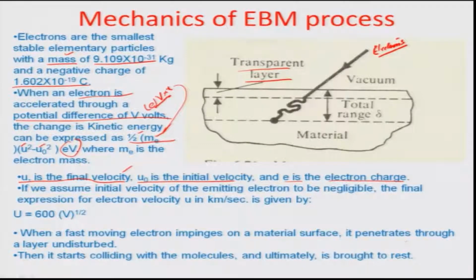we assume that immediately after emitting, the electrons all had zero velocities, or maybe very small velocities which are hardly comparable to the overall accelerated electron velocity that would result because of the perforated anode system. You already are aware of how the cup shaped tungsten filament creates the electron beams and focuses the electron beam into a perforated anode.